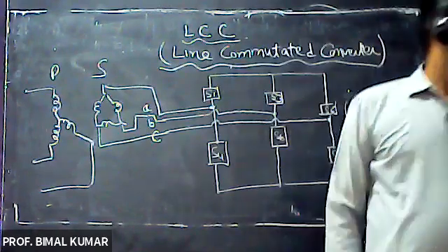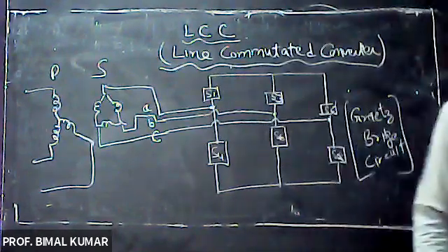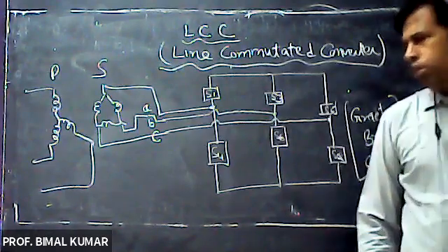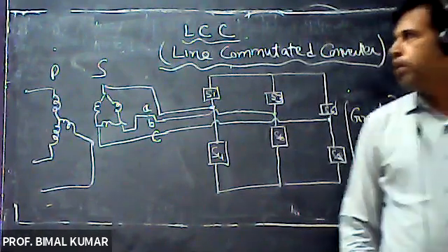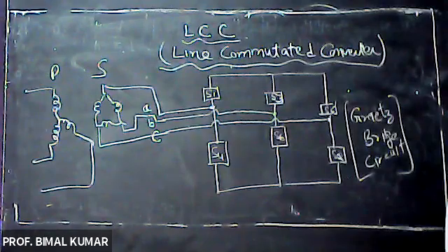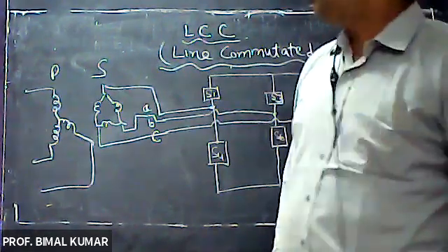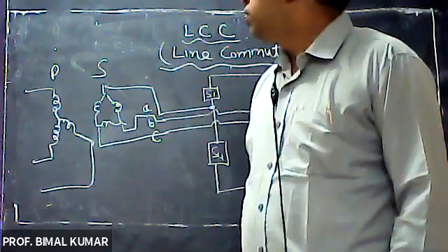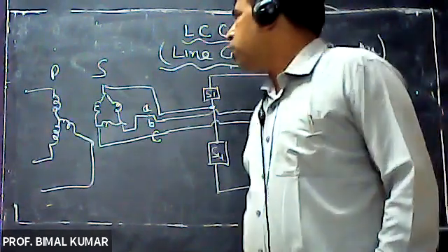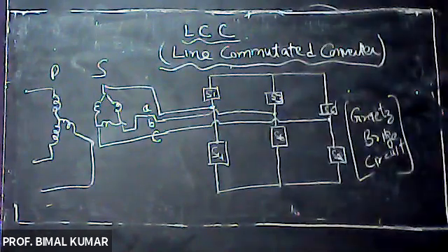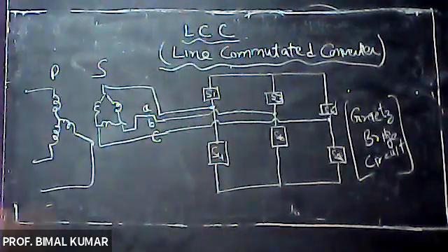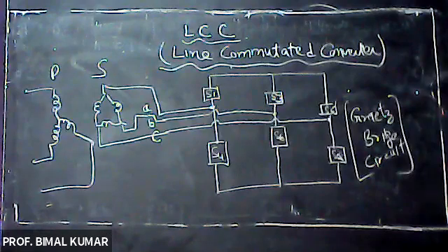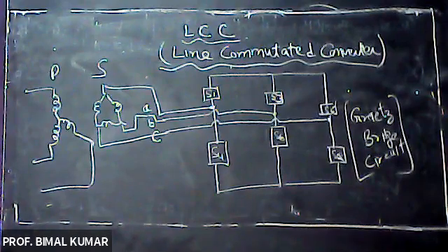Now, one thing that is very important: the auto transformer is a device, and I think you must be aware of it. It is a single winding transformer with the help of which I will be able to change the voltage at any instant. In the ordinary case, we are using two different windings, but in case of the auto transformer, we are using only a single winding.